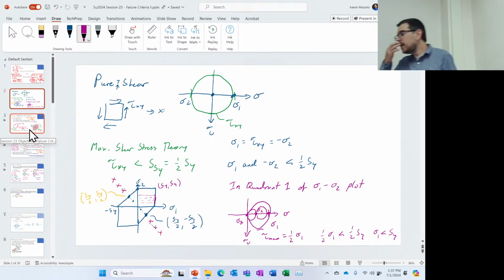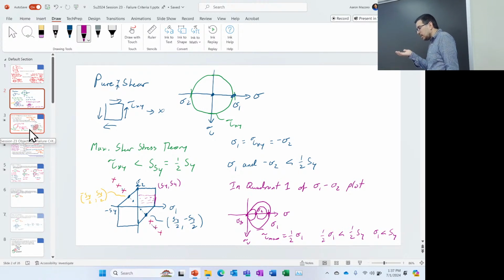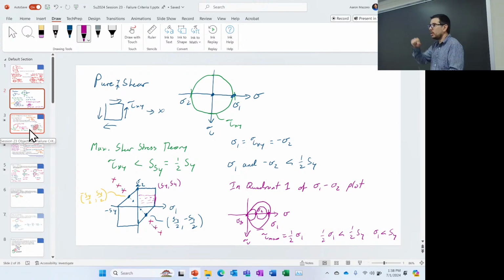So essentially, maximum shear stress theory also is based on distortion. If the element distorts, that's when you're going to have failure, right? And even in uniaxial loading, when I do a tensile test, I am distorting the material. If I were to somehow magically pull the cube apart, you know, I talked about it sinking to the bottom of the ocean, so that's all compressive.